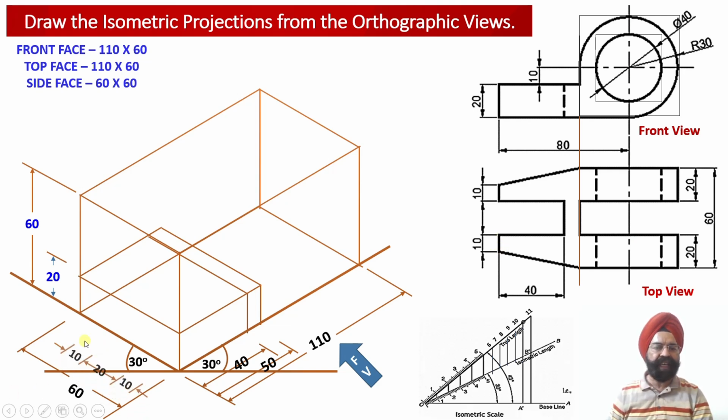So now we can see, as we look from the left hand side, from the center point, 10 millimeter offset and 10 millimeter offset. So this will provide us with these 2 points, that is the 20 millimeter rectangular slot width over here we have been able to obtain corresponding to this portion of the web